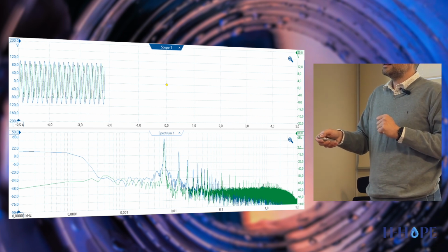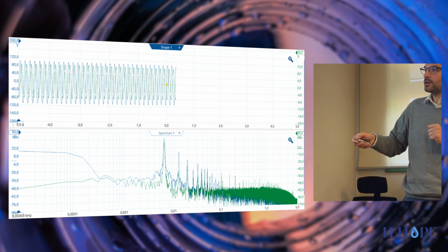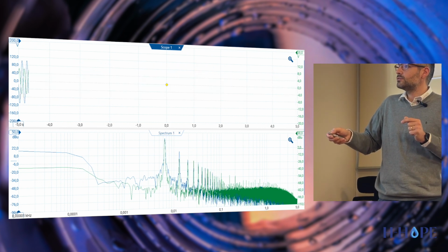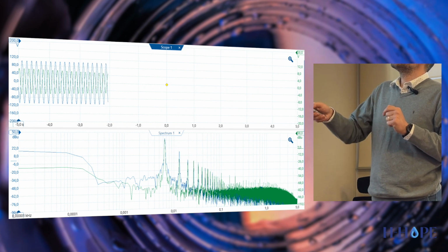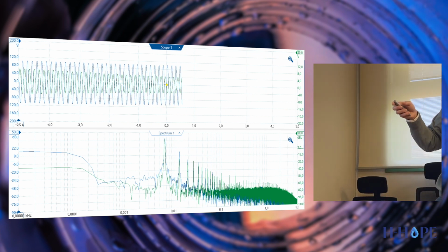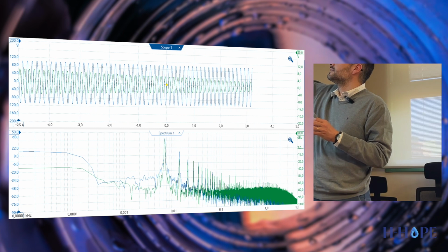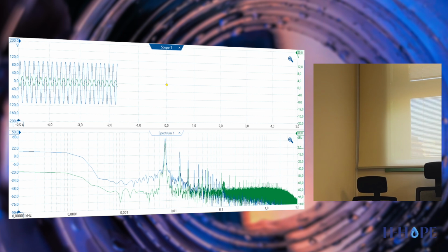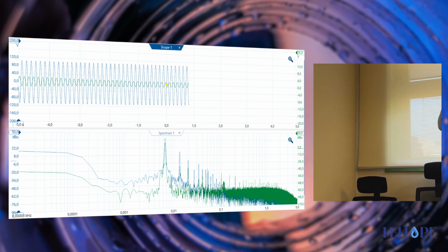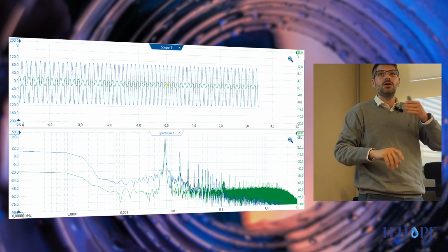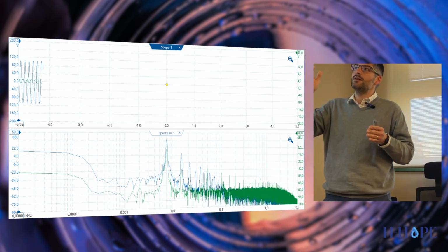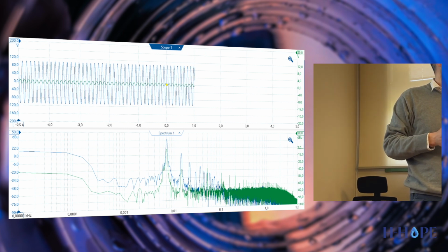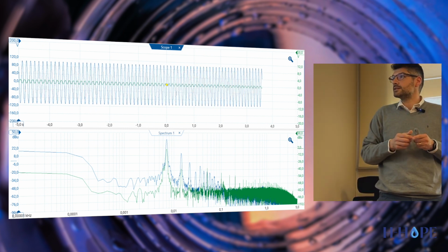In green, this peak here will increase its contribution. We can see that the output voltage is increasing. Another thing we can see is a little time difference between the peaks of the excitation voltage and the output voltage. This is due to the hysteresis implicit in piezoelectric materials.